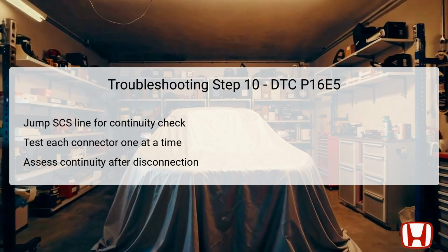It is essential to determine if any break in continuity results when disconnecting a particular connector, which indicates that particular circuit segment is intact while others may be compromised. If continuity holds, it requires repair of any shorts noted across the LIN wires to ensure proper communication amongst components.